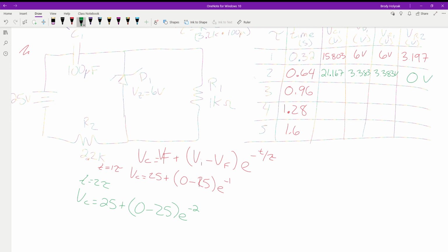There will be a little bit of voltage on that because we still have a little current, but it's going to be negligible. We're talking less than probably 50 millivolts at the most. It's still operating. There's still a little bit of current flowing. Partial, because this thing is choking it down.